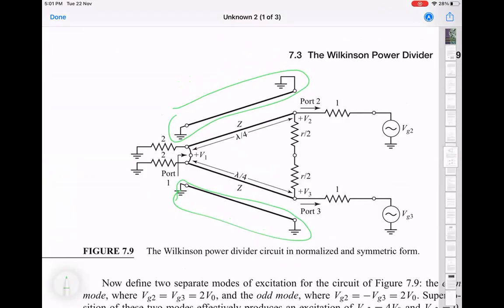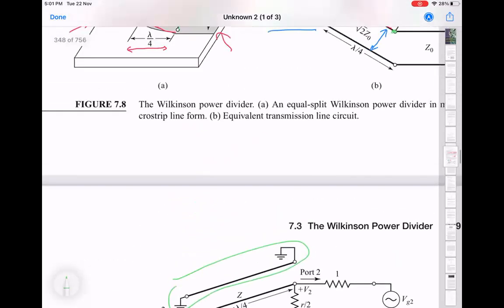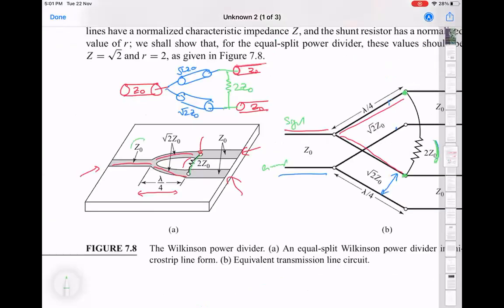And this connects with what I had explained for the resistive divider when Panya was asking about starting and stopping. What do I mean by the necessary parts? Let me go back here. These 50 ohm feed lines really serve no purpose in the active performance or the functioning of this device. They are just allowing us to send the signal to a 50 ohm port, right?